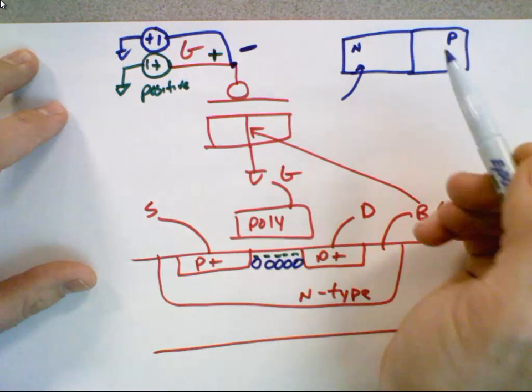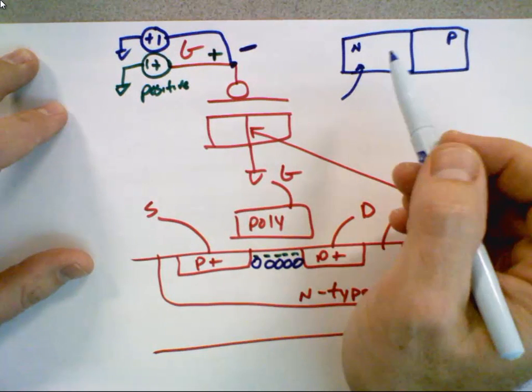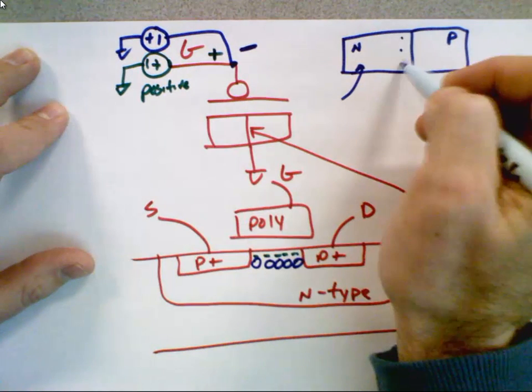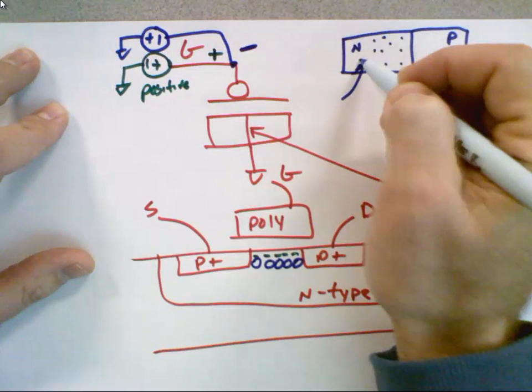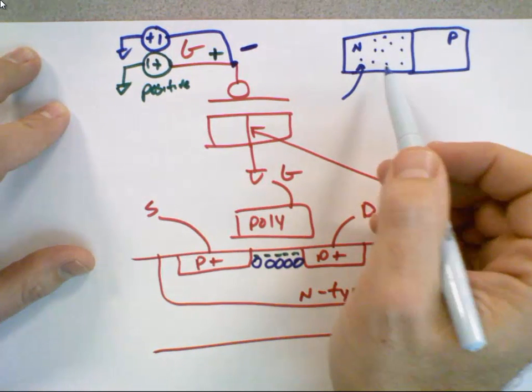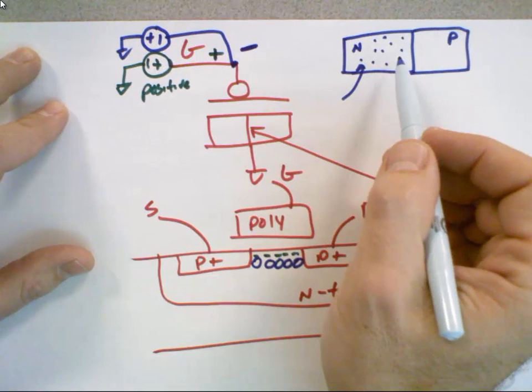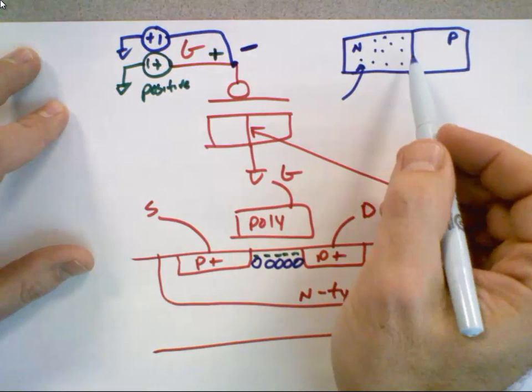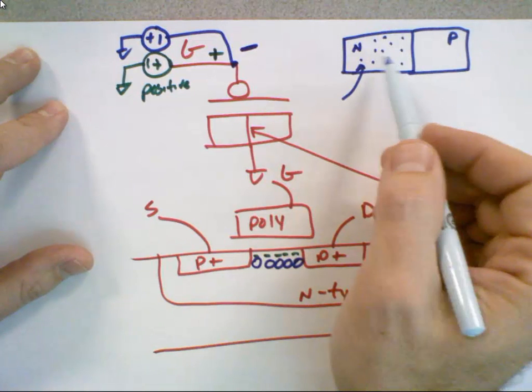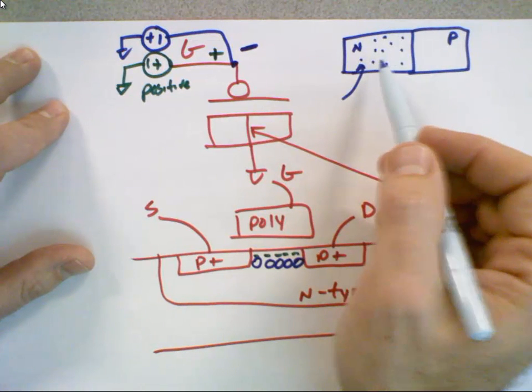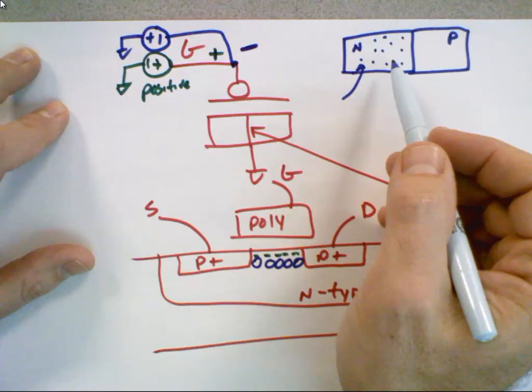Okay, so people say it's negative. The problem is you have all these free electrons, right? The way you get that is you add an atom that has 5 valence electrons instead of silicon's 4 valence electrons. Electrically, though, this material is neutral. Just because I have free electrons in here doesn't mean there's a negative potential. Same thing here.